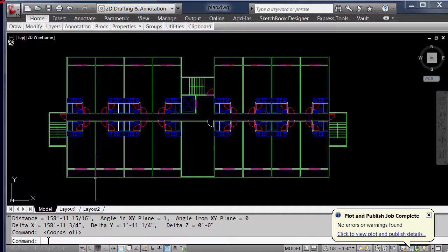So with that said, if I'm experimenting, 1/4 of an inch equals a foot. Remember in DT 1230, I mentioned that the front part of that equation, the 1/4 of an inch, that side of the equation has to be 1 inch. So I have to multiply the back side by 4, actually by 48, because it's 4 feet times 12 inches per foot. I'll run through that again. Hopefully I'm not going to confuse you.